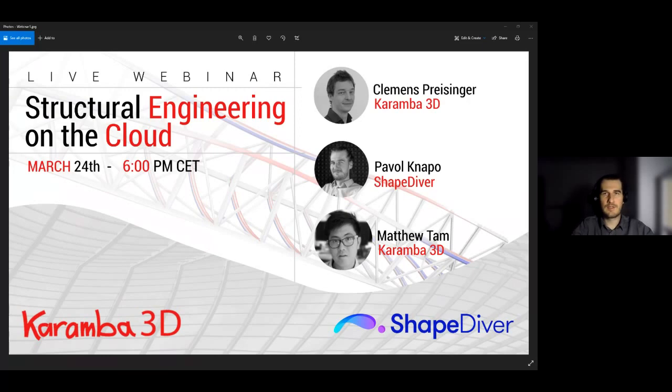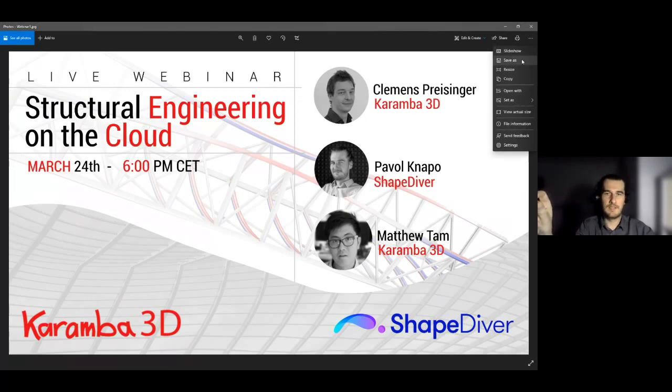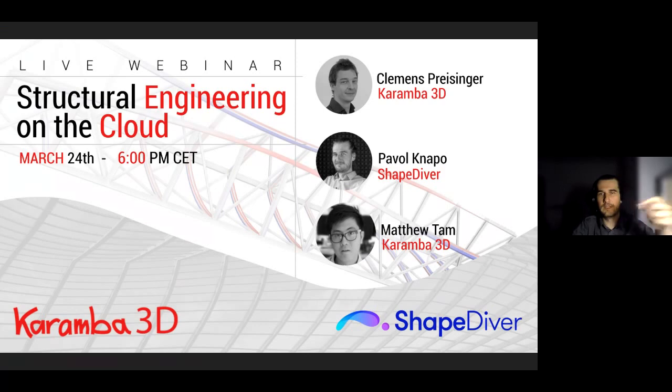But in essence, how to set up the model is that you create, for example, for this steel connection detail, spheres as the grip points, as simple mesh spheres in Grasshopper. Important is to give them an understandable name, not just use the default component name. This is important to then reference in the code, where you can set up the interaction groups, and this is covered in the tutorial. So you need to prepare the definition before you upload it to ShapeDiver, and then you reference the gripping point in your code.